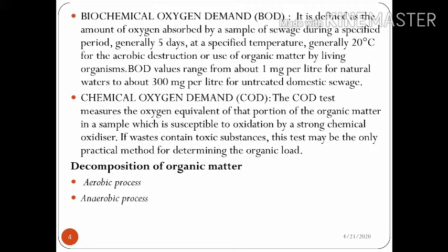Chemical oxygen demand. Chemical oxygen demand measures the oxygen equivalent of that portion of the organic matter in a sample which is susceptible to oxidation by a strong chemical oxidizer. If wastewater contains toxic substances, these tests may be the only practical method for determining organic load.